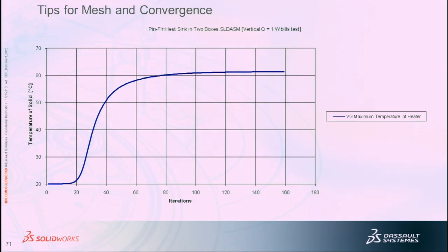In that case, just make a big computational domain, make it very coarse, and see what it tells you. There's a lot going on behind the object, and you need more mesh behind it to resolve what's going on. If you're just studying the object, the surface mesh will tell you what you need to know if you want the forces. And like Bill said, you'll still have wall effects. Typically in a wind tunnel, you want the object to be 7 to 10% of the throat area, and that minimizes the wall effects. If you do that, you'll see effects on the edges, but it doesn't affect the result.